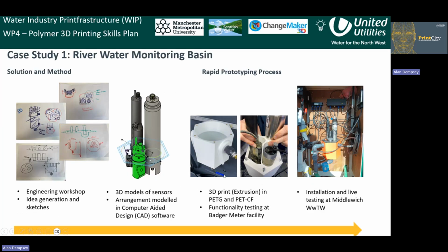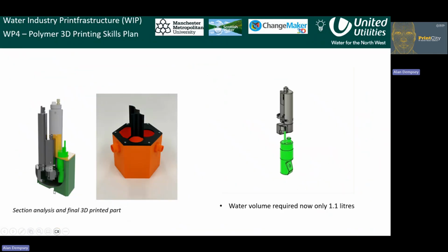Finally, I'll just skip back a slide. Between version 1, lab testing, and feedback, in version 2, we were able to add a hole for an existing pipe fitting, a tap essentially at the bottom. The idea here is that the operations and maintenance team who'll be visiting this system would quickly be able to open that tap on the bottom and flush the entire system out, removing any buildup of suspended solids.